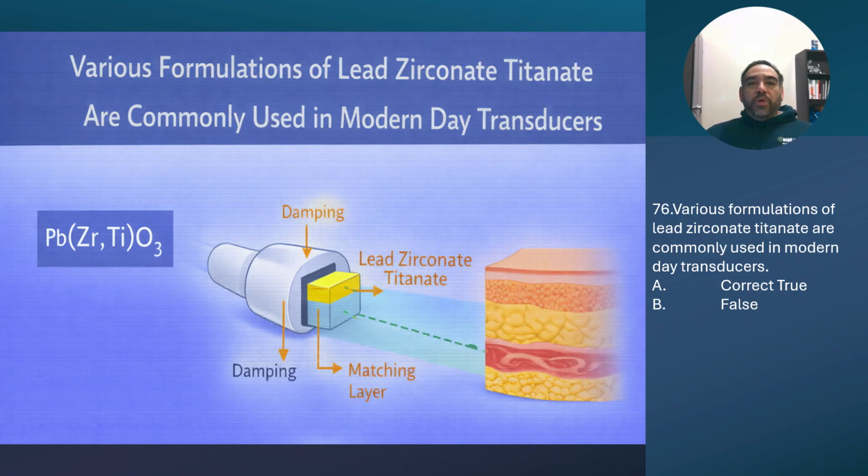And takeaway from these last couple of slides, quartz, remember that was a natural piezoelectric. It's older technology. PZT is synthetic. We have to polarize it for it to become piezoelectric. We can also customize it. So modern ultrasound, we use engineered ceramics, not natural crystals.